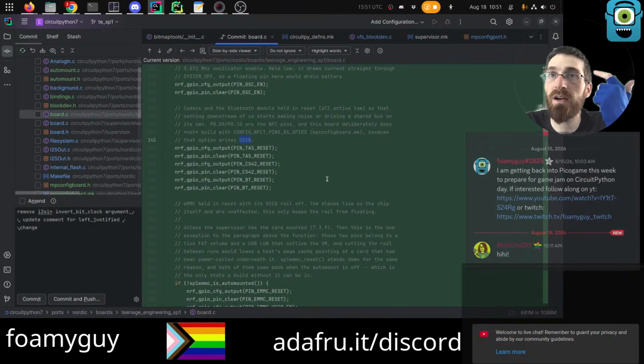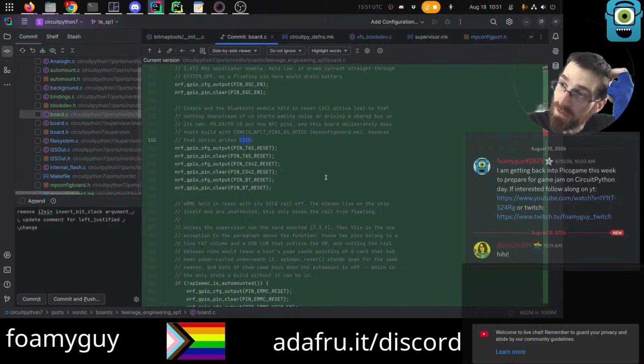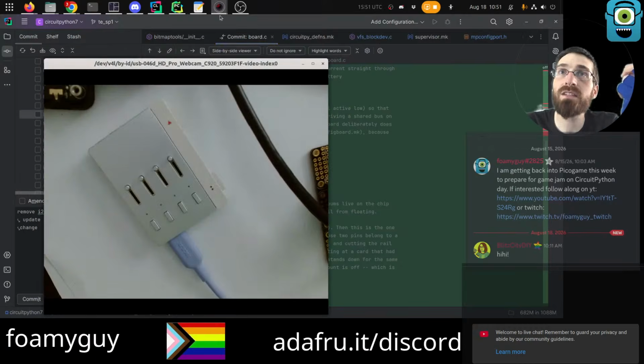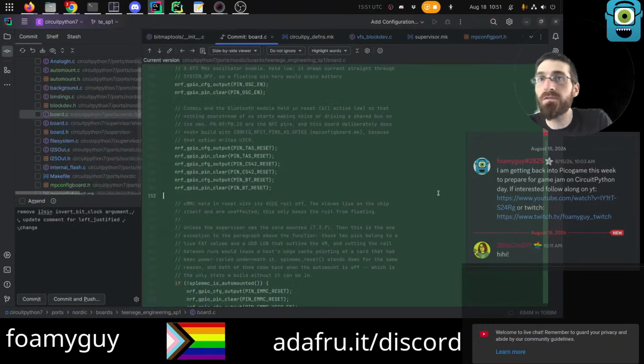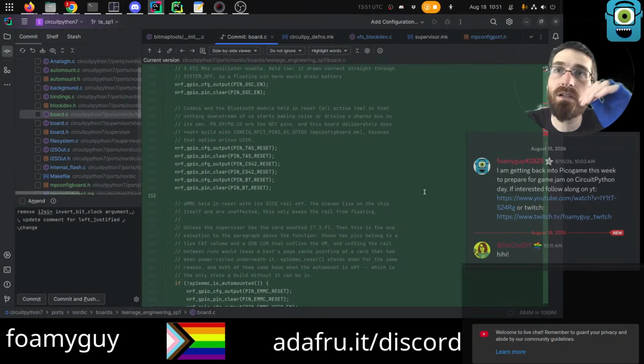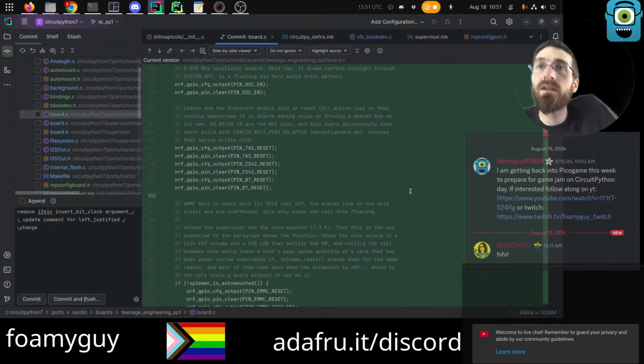It doesn't really have a way to pull the power that you can get to. The firmware has to be running and healthy and listening for this button press in order for the device to be able to turn off. And the only way to enter the bootloader is from a device that is turned off. So if you ever get to a state where you can't turn off, then you can't get to the bootloader either, and you basically just have to wait for the battery to die.